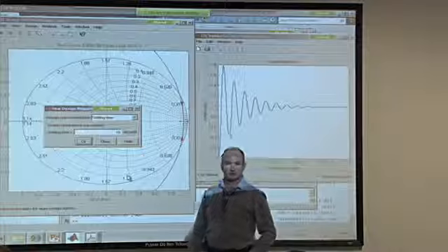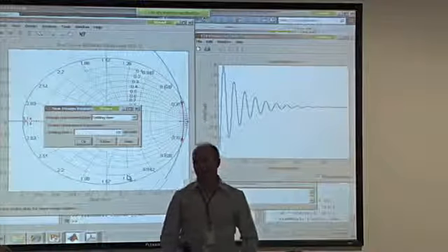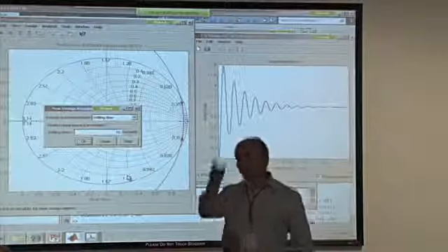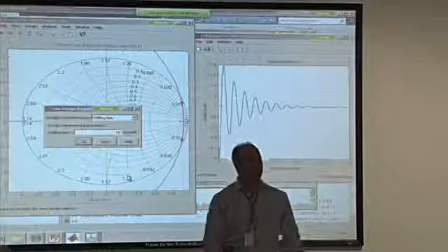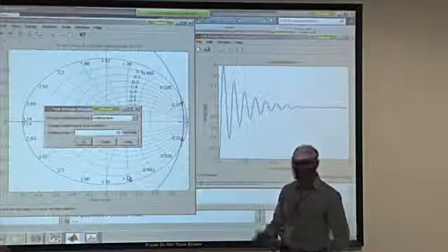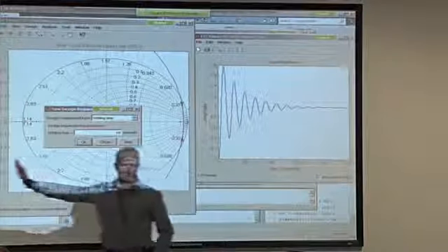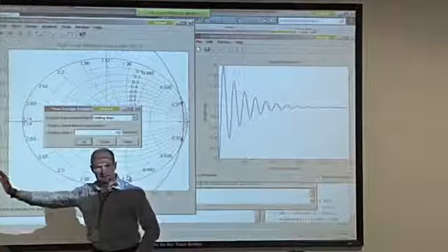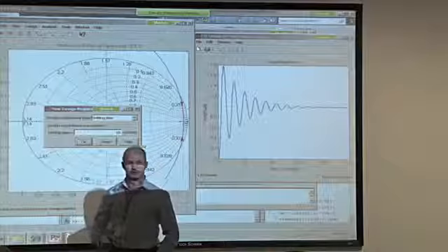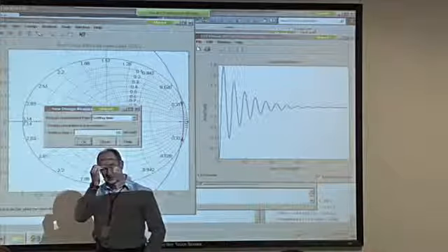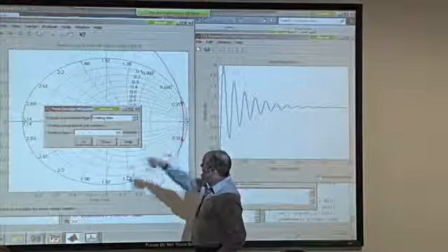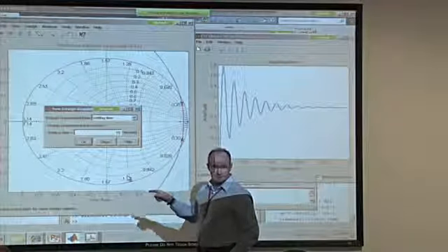What do you think that region is going to look like? Yeah, I think you know. No, but you're very close. No. Well, remember, if we want a fast settling time in the S-plane, it corresponds to moving it to the left, right? So vertical lines correspond to lines of a decay parameter, but they could correspond in some sense to settling time as well. Well, vertical lines in the S-plane correspond to families of concentric circles in the Z-plane.